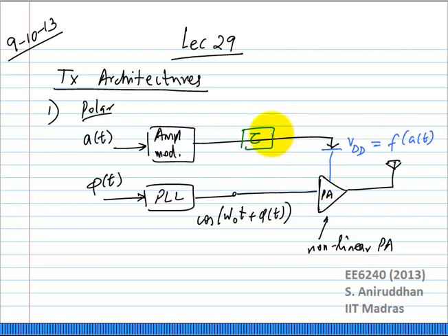If you were to take the same signal in the Cartesian domain, it's a lot easier because the xi and xq paths are going to be almost identical. Managing delays between those two paths is not a problem at all. This problem purely arises in polar modulators.